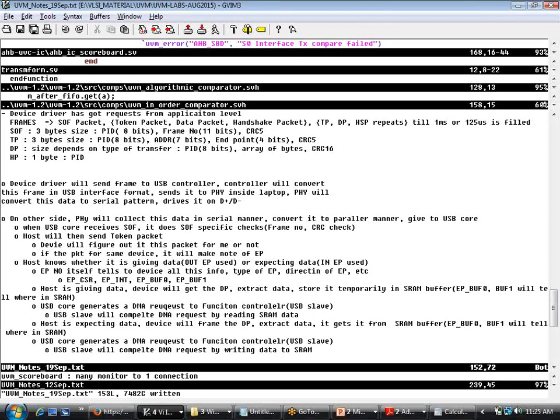The most critical point in all this operation is what? Endpoint number. Each endpoint is associated with registers. Those registers will tell what type of endpoint it is. Is it isochronous? Is it bulk? Is it interrupt? Is it control? Is it in? Is it out? What is the memory space that should be used? All that information, the endpoint number will tell.